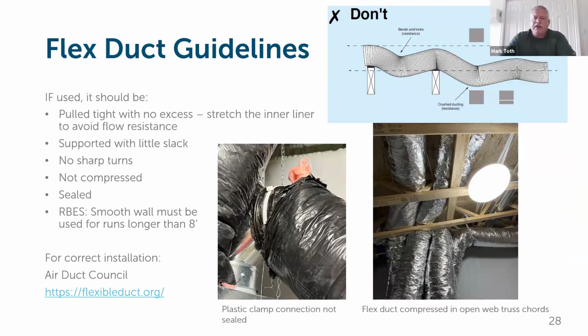Excuse me. Here you can see about the flex duct. Obviously, there's ways to do it and there's ways not to do it. The picture on the top that we talked about, a snake, like a slinky, you don't want it to look like that. Airflow is going to be restricted. We talked about elbows being 15 feet. Well, essentially here in that piece, you have like 1, 2, 3, 4 elbows maybe in that very short piece of duct. And the inside of that is not smooth. It's got that metal wire that runs through it, so it's bumpy on the inside like a corrugated pipe.